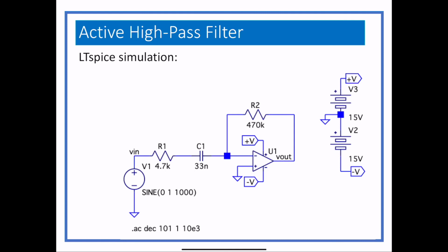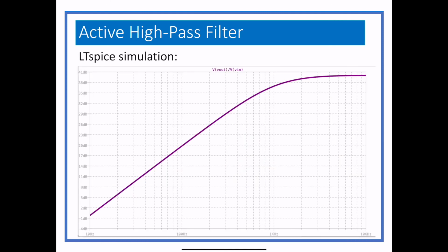And when we do that, we get mostly a nice curve. The high frequency gain is 40 dB, which is good. You'll notice I cut it off right, it's not extending as far, and there's a reason for that. But the 3 dB less than that, there's a little tiny blue arrow, which is a little hard to see, but we go over and we find that value, and we drop down, and we find that that does happen at 1 kilohertz, which is good.